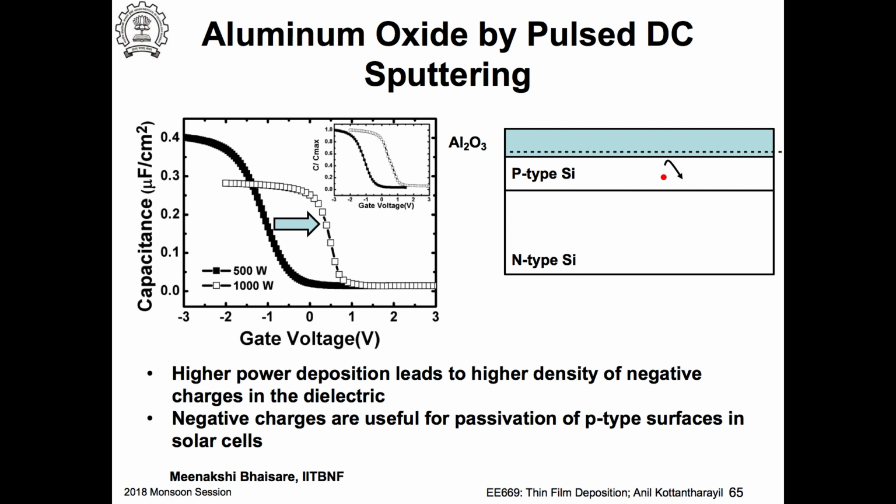This would repel electrons and attract holes. The problem comes when they are together, so by separating the electrons and holes, this reduces the recombination rate. In any of these recombination equations, you have the product of electron and hole concentrations, np, so you're decreasing one of them.